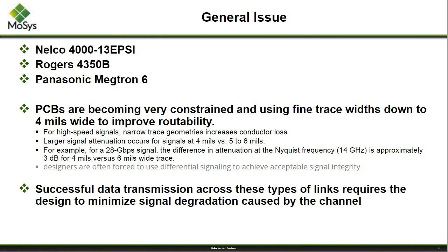The other thing that you want to do, a good rule of thumb, is to be as conservative as the layout lets you be. So you want to try not to narrow down your trace width. For many high-speed signalings, you want something in the 5 or 6 mil wide range. Narrowing it down to 4 mils, which quite often you have to do for things like escapes from very dense BGA packaging, going from an internal ball to escape the routing out to the outer layers, forces you to have minimum width signal traces. You want to minimize the amount of time that you're doing that.